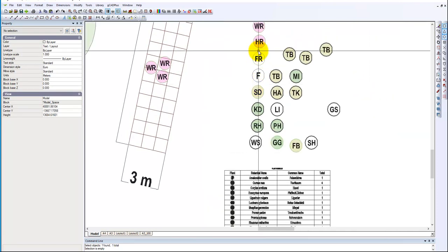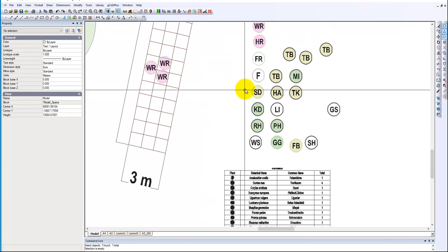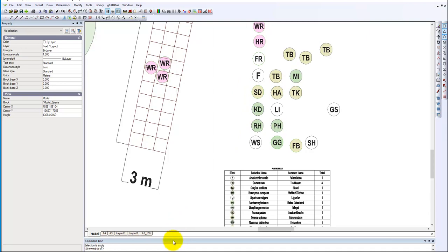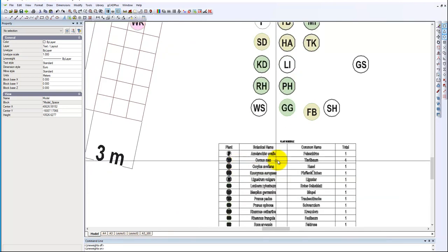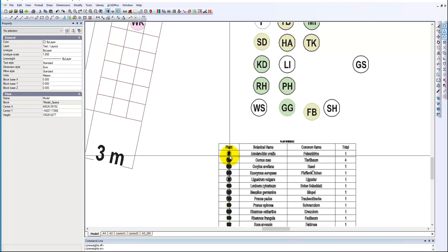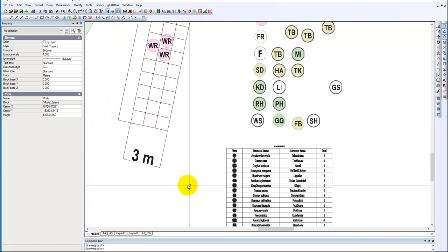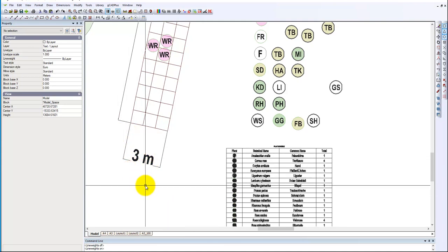If you look at this group of symbols, some have got filled colors, some have got line thickness. Let me illustrate by taking off line weight and putting line weight back on. Can you see the problem here in the plant schedule with a mix of line weights applied and line weights not applied? Consistency here also is seen in the definition of the dimensioning style.